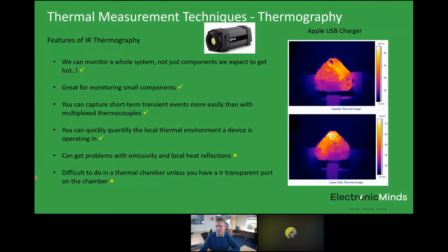I think the last question here is about liquid cooling tube isolation methods from the switch. I think this question is about how you electrically isolate the liquid cooling tube from the switching device. This is the Litz wire with that very thin layer of tubing down the middle. The examples we've seen, and we've spoken to a few manufacturers about this, are actually a plastic tube that goes down the middle of the winding. And then when the winding comes out, obviously it needs to split, with the electrical part going to your electrical circuit, and then the tube goes off to your water cooling circuit.